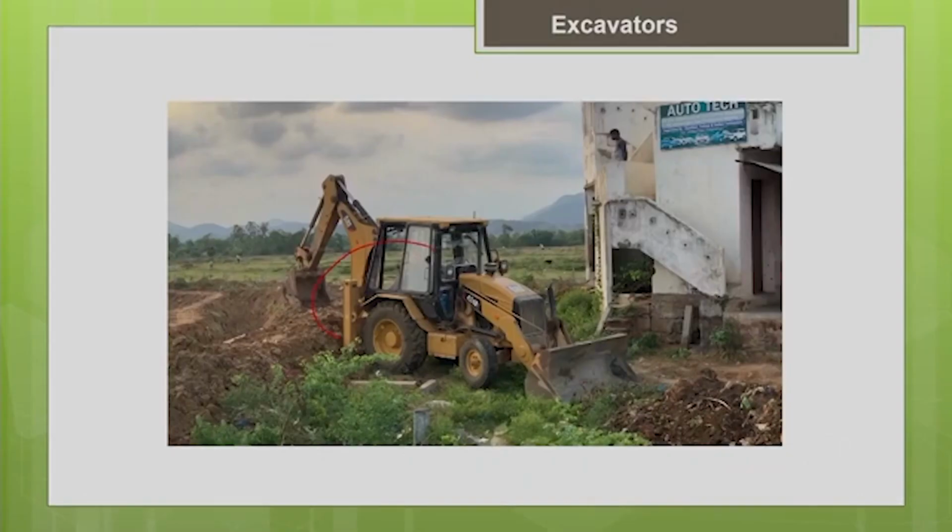So this is a wheel mounted loader. You have to carefully note that you have to extend this outrigger. You can see this outrigger, right? This outrigger you have to completely extend on both the ends and make sure that the load is transferred from the outrigger to the ground. This is very important from the stability point of view. This is because the machine is wheel mounted.